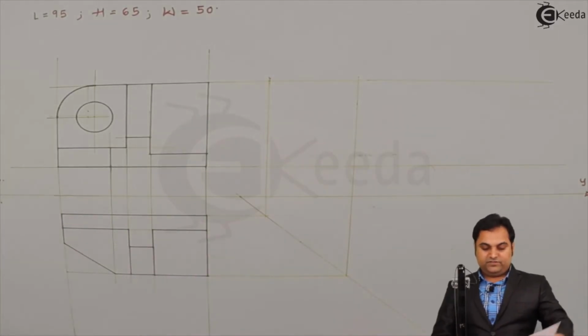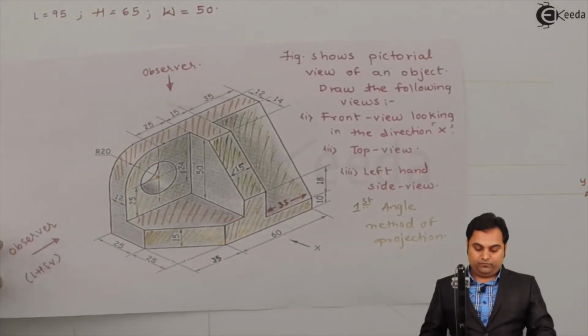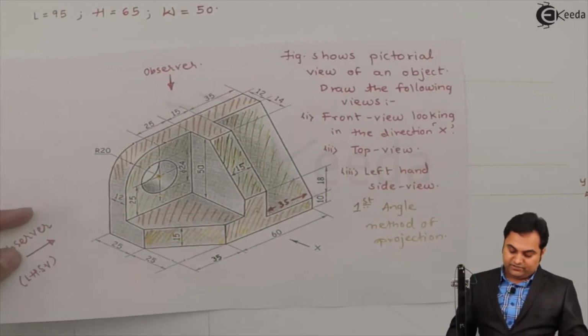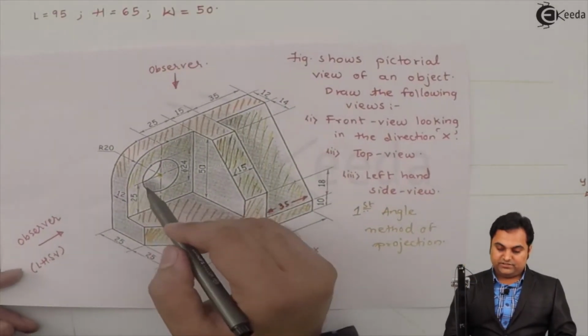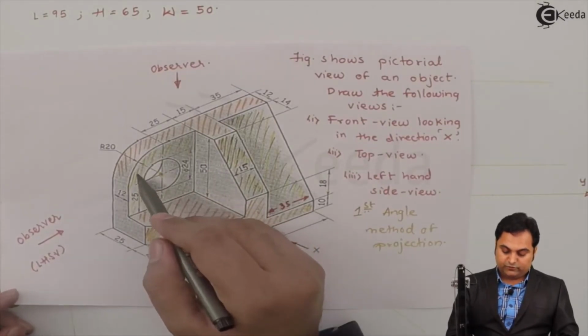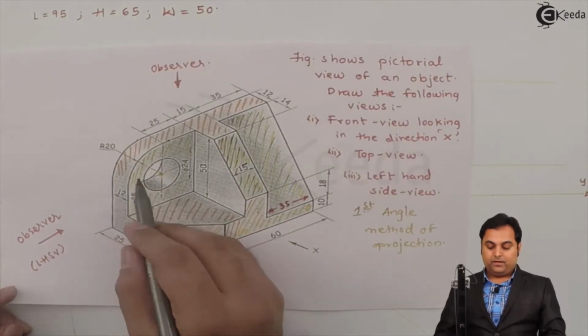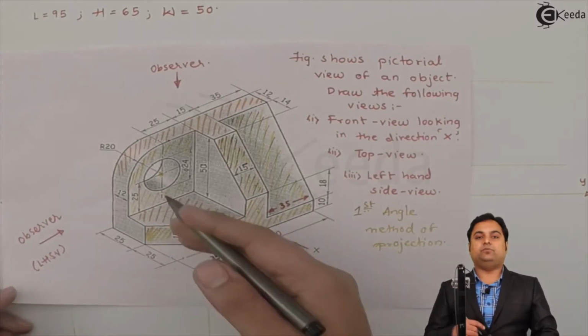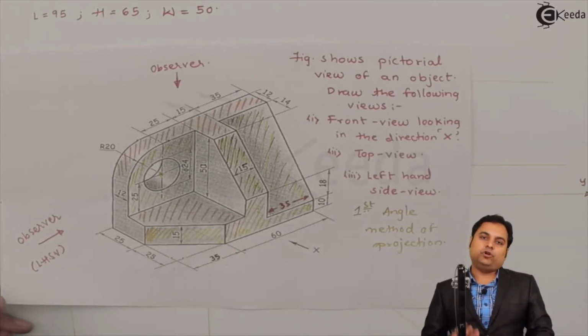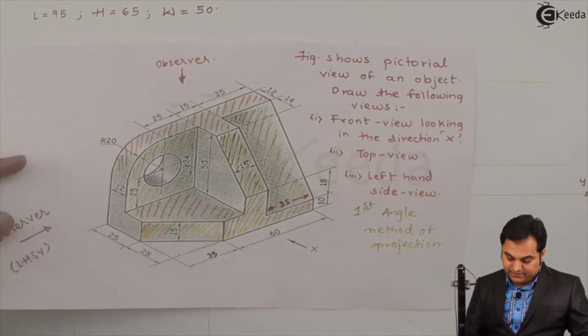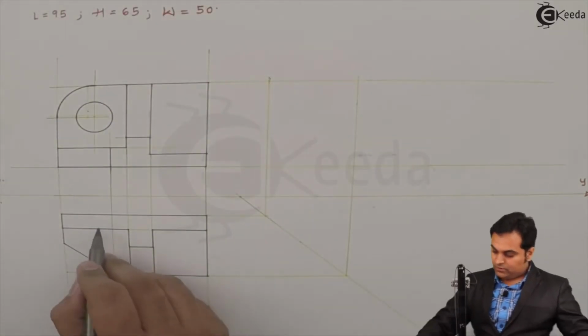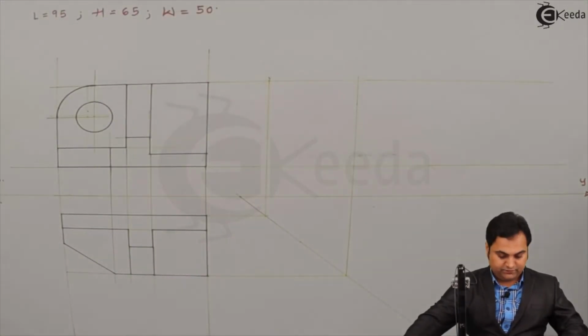So here is the visible portion from the top. After that, if we see, there is a circle inside this disc which is of 12 mm width, but this circle won't be visible from top. So it has to be drawn hidden, and it is there in this plate. So first I'll get the center of the circle.